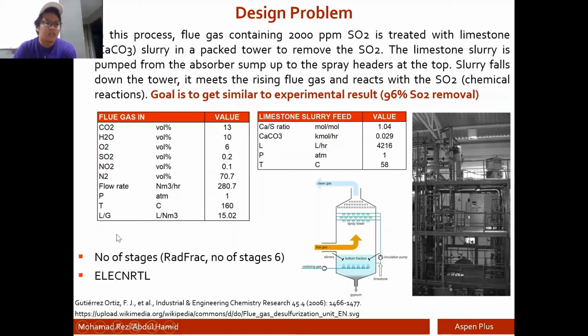And then other important information that I will input into the simulation is I will use RadFrac block, I will use RadFrac column, and I will choose number of stages of 6, and I will be using electrolyte ELEC property method, which stands for electrolyte non-random two-liquid.